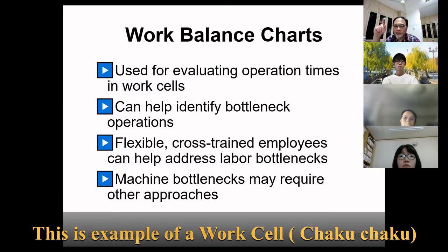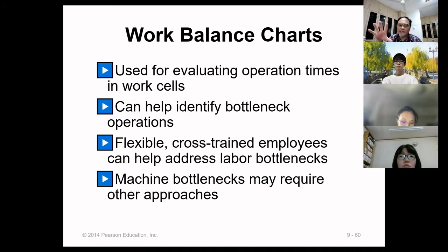So we have conditions as well as assumptions. That's very important. That's why I'd like you to have analytical thinking, so that when you see a problem or a situation, you can visualize how to model the problem. That's one of the most important things. Another tool which is used in layout is work balance charts. Work balance charts are used to evaluate operation times in work cells, especially if there is more than one worker.